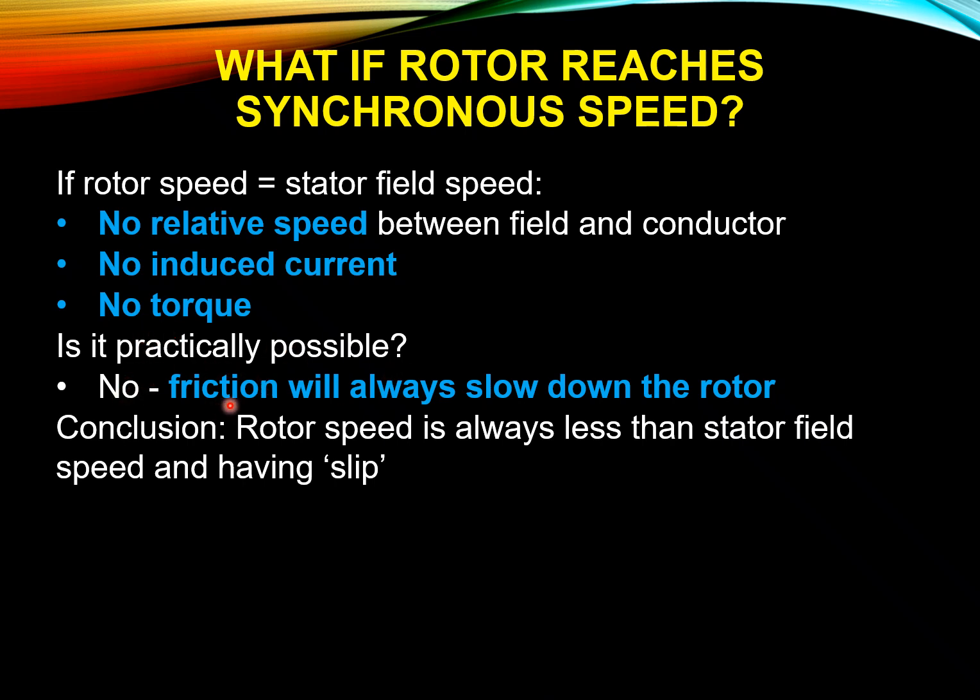No. Friction always slows down the rotor, so there will be a slight gap. In calculation you can calculate it to be the same, but in real life it is not possible because friction will always slow down the rotor. As a conclusion, rotor speed is always less than stator field speed, having a slip. So rotor speed plus slip equals stator field speed. That is how we can conclude.